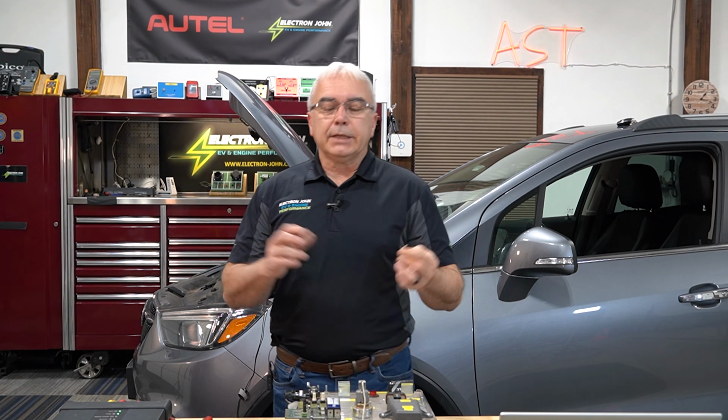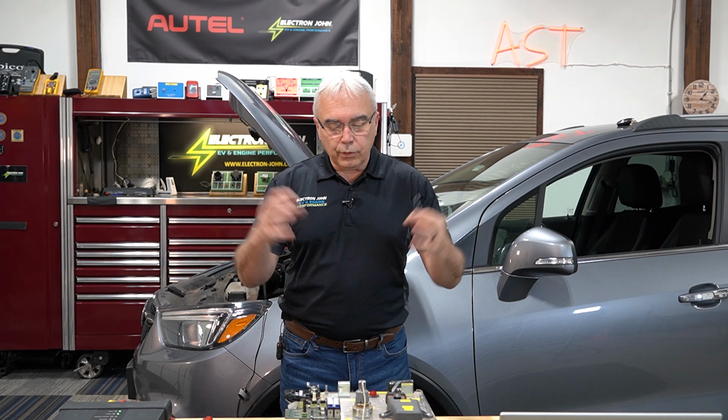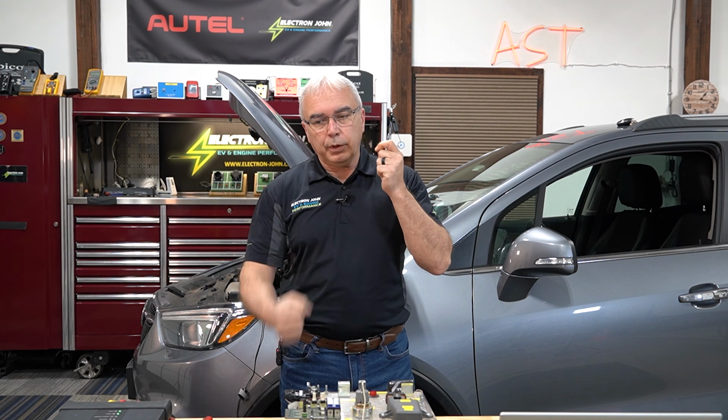And you might say, hey, that's not very easy to do anymore on today's cars because of coil packs and everything else. There's all kinds of adapters. We showed you some of them in the preliminary YouTube video, so if you haven't seen that yet, definitely seek that video out. There's paddle probes that you can use. There's the inductive pickups. There's even a set of spark plug wires that you could take a whole coil pack off, put a spark plug wire on, put it back down. Then you can use your high tension lead and clamp right around it. So again, just get the right type of adapters that you need here.